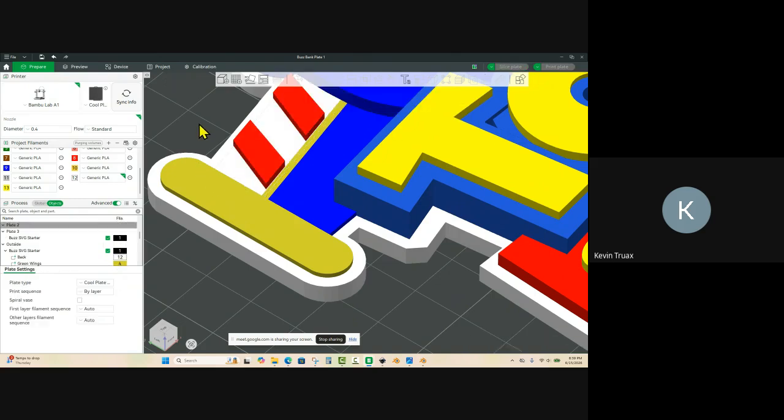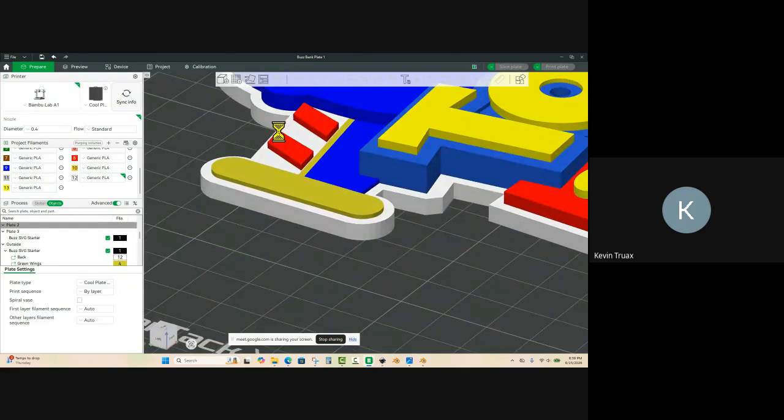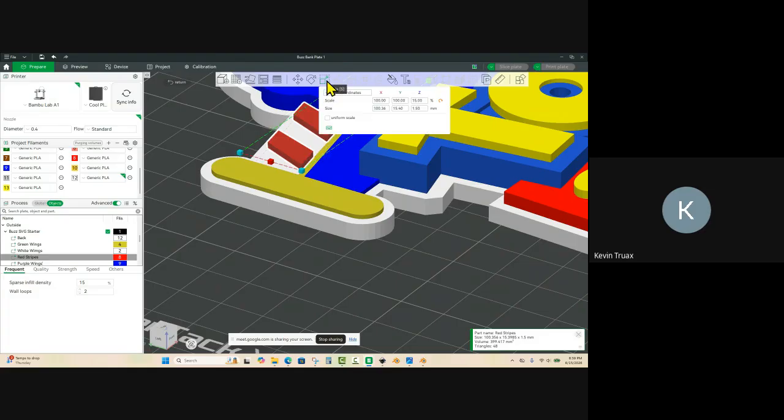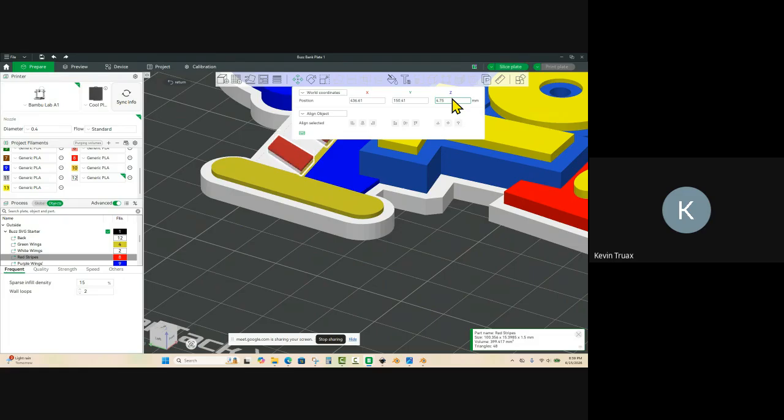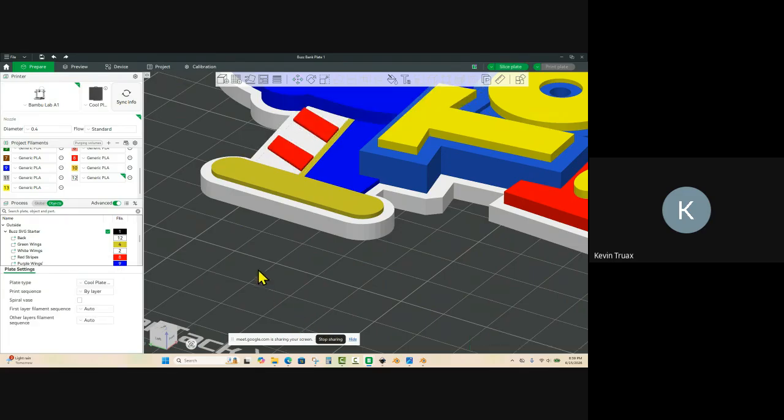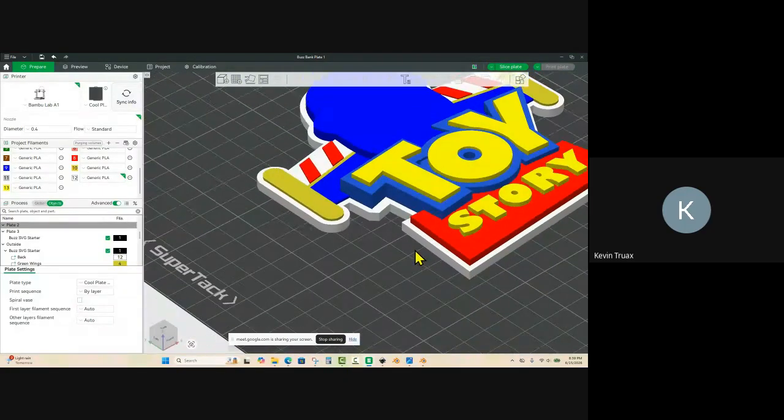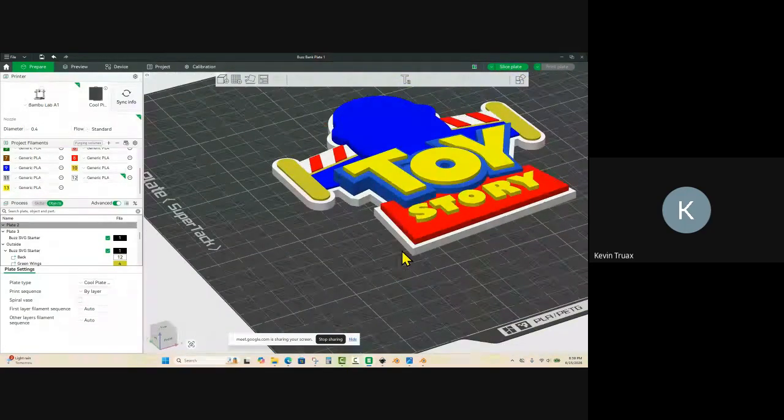And now this is a little bit different. Our red stripes, let's go ahead and I'll click our red stripes and take a look at the thickness. They're at 1.5. Half of 1.5 is 0.75 of a millimeter plus 4. So that height has to be 4.75. And I deliberately, just for fun, made those just a touch, 1/4 of a millimeter deeper, just because I thought it would add some visual interest.